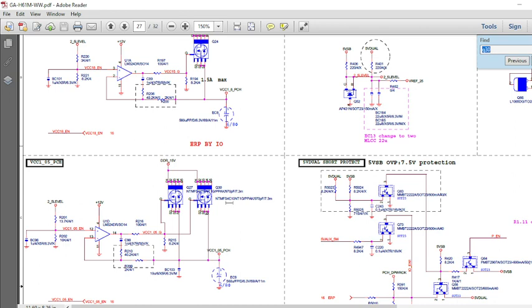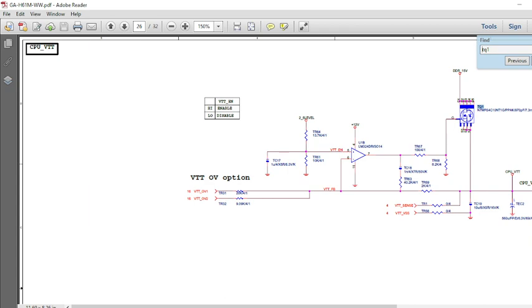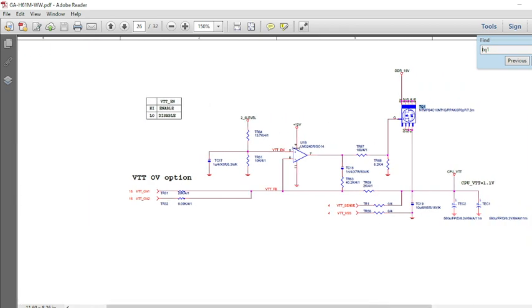Next is CPU VTT. For that we have TQ1. Okay, this is the CPU VTT. Again you can check, the LM324 is going to control it, as there are 4 op amps. The first was controlling the 1.8 volt line, then the second was controlling 1.05, and this is the third. The same op amp is controlling this CPU VTT. Again 1.5 volt of DDR is given as input for this TQ MOSFET. This MOSFET you will find, I think, below the CPU socket.